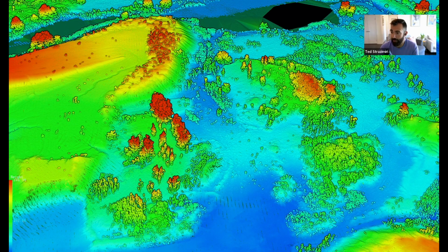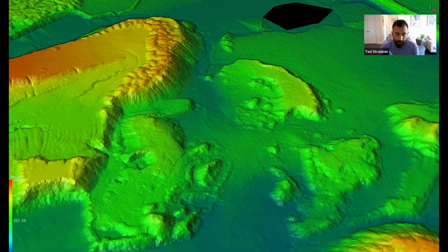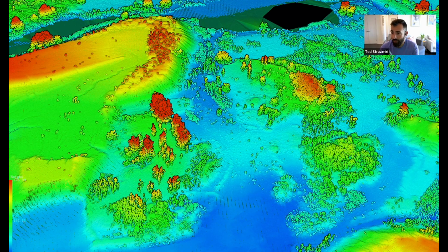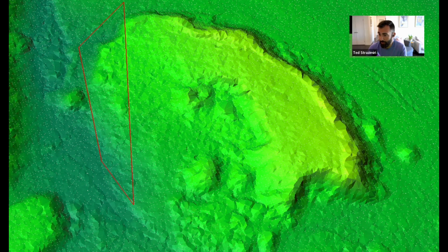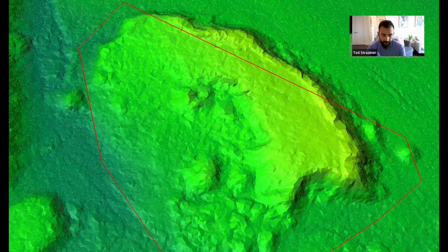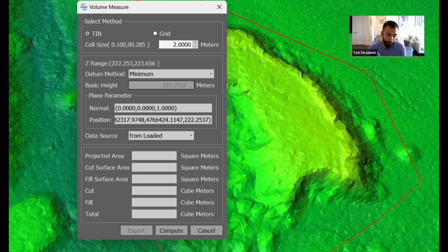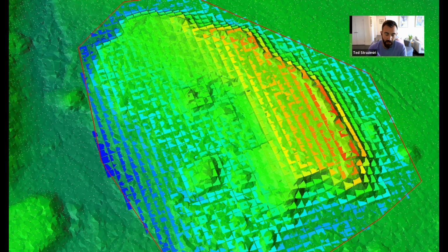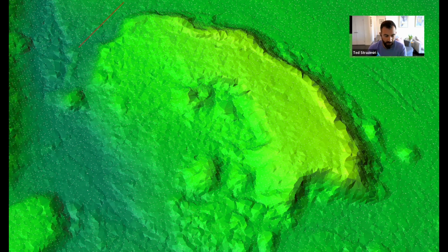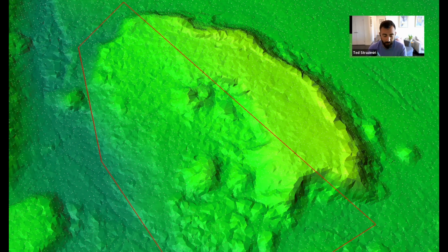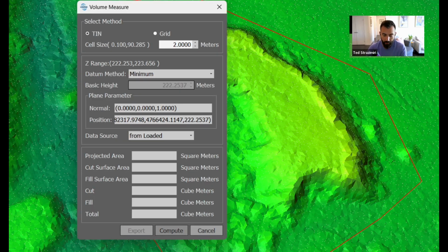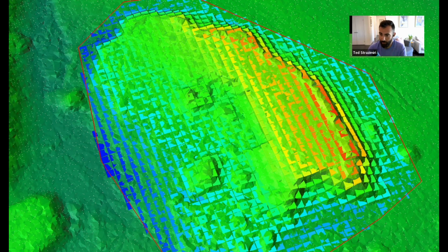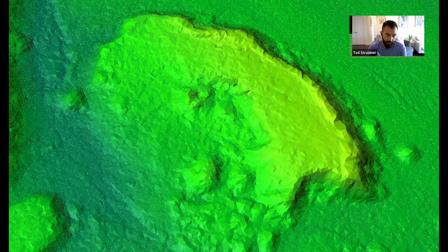And then if you're doing this once a month, once a quarter, you really only need to do this once. You have the locations that you're measuring, and you can compare them over consecutive data sets. Everything will just fit right in. LiDAR doesn't work with ground control points like photogrammetry does, right? So you set your base up and you fly that mission, and everything should line up if you set the base up correctly. So the efficiency really starts to grow when you get into these situations where you're at the same location multiple times. It gets progressively faster each time, essentially.